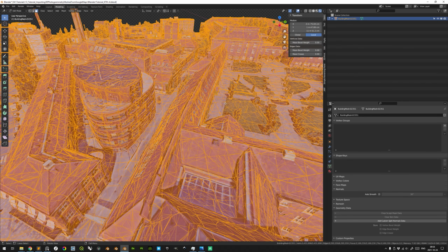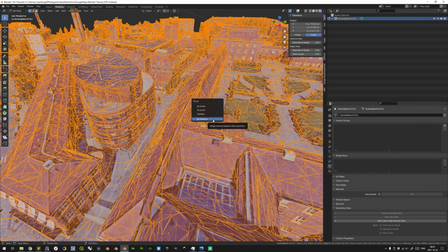And since all the meshes were imported as tiles and portions of the objects situated side by side, we can reduce some complexity by simply, if we change here to vertex mode, see the vertices more clearly. And with everything selected as is, we can press the M key on the keyboard, and then we can collapse or merge these by distance.